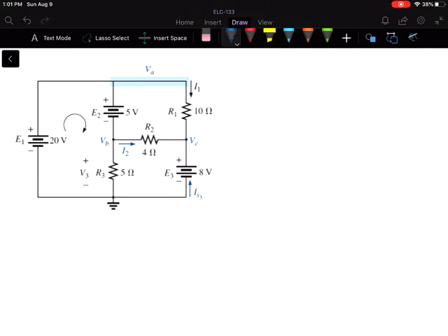However, what we can do is use our Kirchhoff's voltage law and Kirchhoff's current law to analyze the circuit a little bit further. So notice right here, I've drawn a loop in here. If we do a Kirchhoff's voltage law equation for this particular loop, and I'm just going to draw it kind of bigger, notice we know this voltage, we know this voltage, this is the only unknown, so we could solve for that. So let's write our equation for just this particular loop.